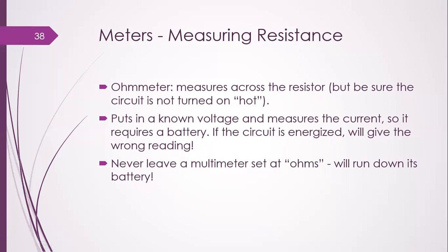So always disconnect or switch off the meter if we do not need to use it, specifically for digital meters, because they are continuously energized if you leave the meters on. Analog meters too, if not in use, we should also switch off as with digital, then your battery would be safe.